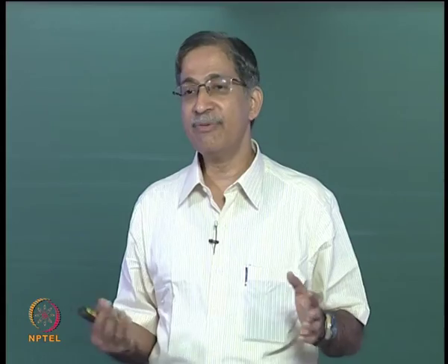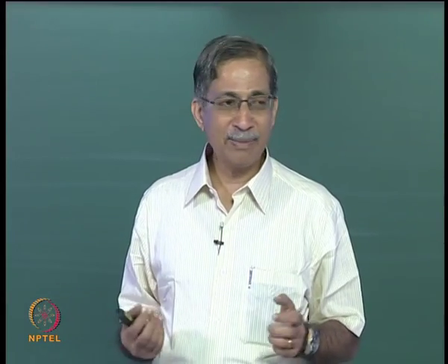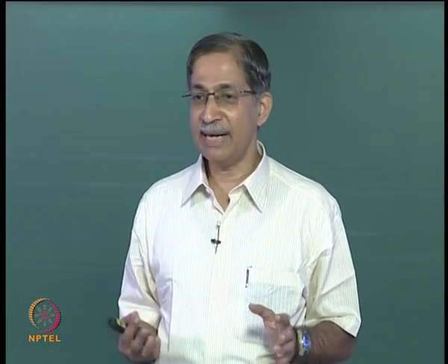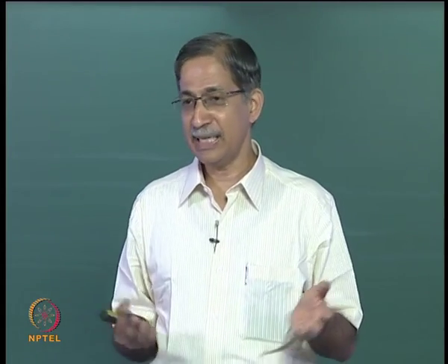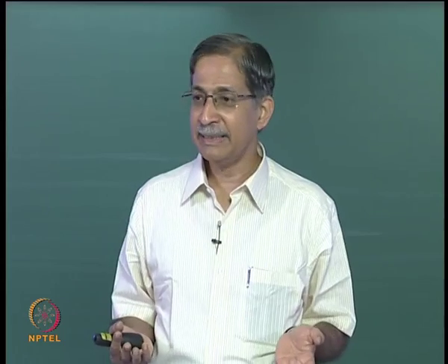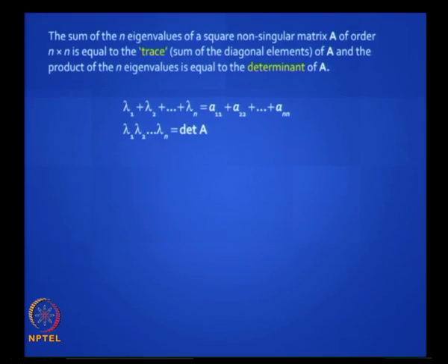They are called natural frequencies, and you have probably heard of the phenomenon of resonance. When the excitation coincides with the natural frequency, then you have large amplification in the response. So that is how important it is to study eigenvalues.